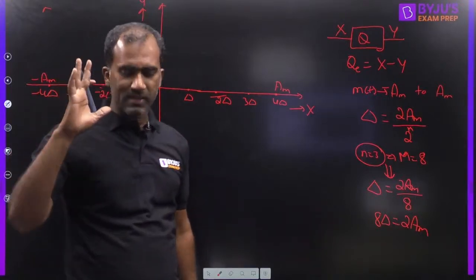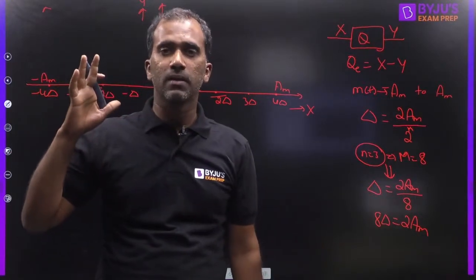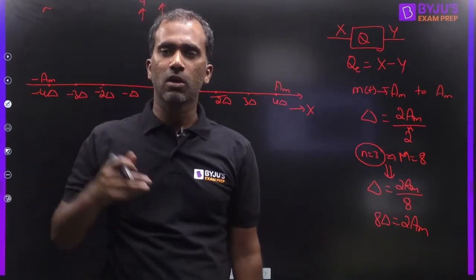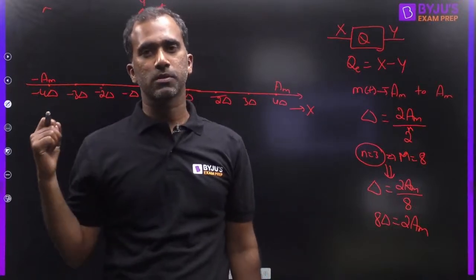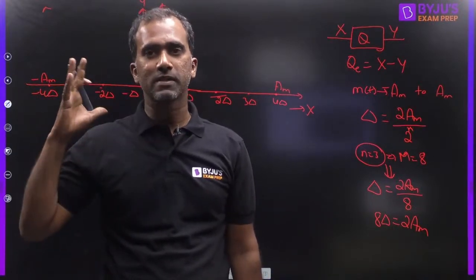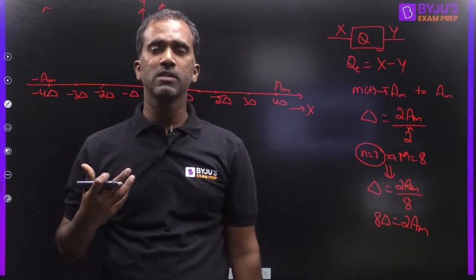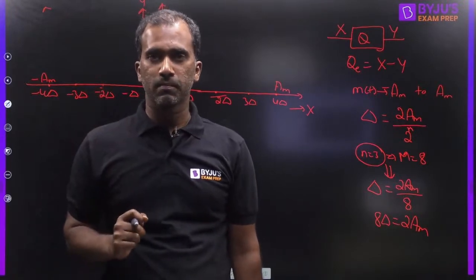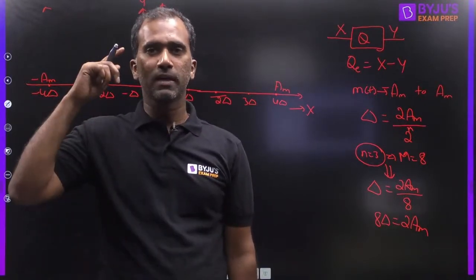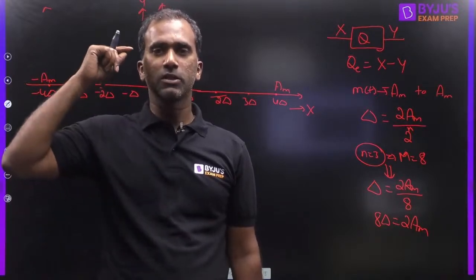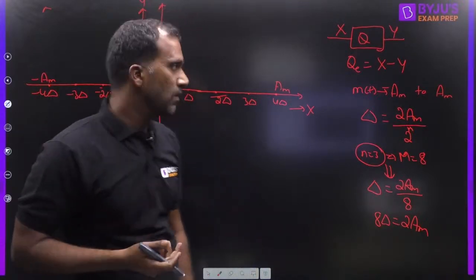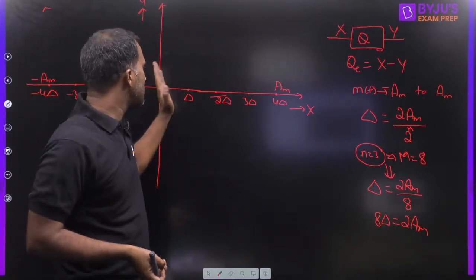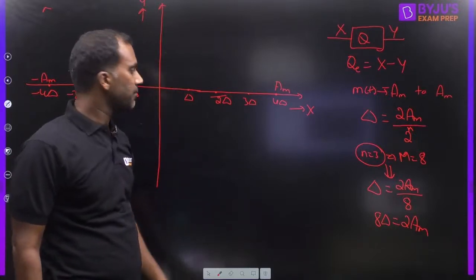Finally, the basic idea of designing a quantizer is to get the least amount of error possible, or the average error or quantization noise power should be as small as possible. That is the basic idea of designing a quantizer. An efficient design of quantizer means we should get, on an average, for all voltages combined, the smallest error possible. That is the only thing that should be kept in mind while designing a quantizer. So generally, to get the minimum possible error, we take the midpoint of each region as the quantization level.